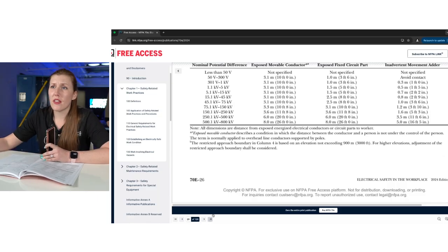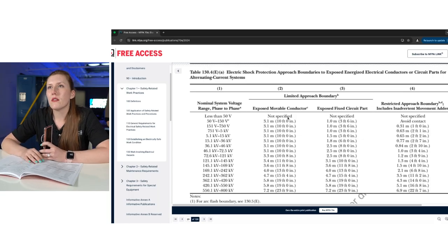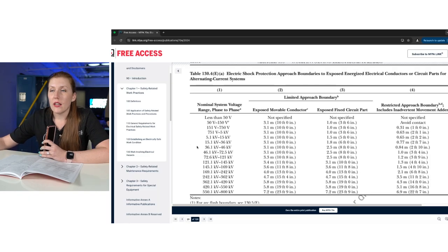The gloves, that's another one. So, you know, you're protecting yourself against these shock hazards within the restricted approach boundary. You have to have your insulated gloves with leather protectors, is what it used to always say. Well, now it's just protector gloves, because there are approved protector gloves that are not made of leather out on the market now. Leather protectors are still by and large the most common, but they understand that what's available and what's been approved needs to be allowed in the standard, because why not? It's been approved, it's been tested.